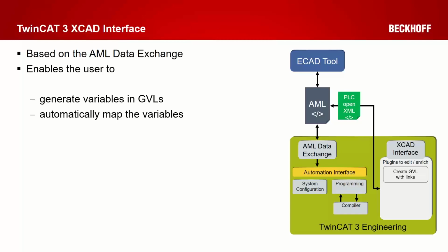If we are talking about naming conventions, we will see that the naming is done totally different on ECAD tool side and TwinCAT side. For example, on the ECAD tool side, names often have special characters like an equal sign, a plus, a minus sign, and these special characters aren't allowed on the PLC side.